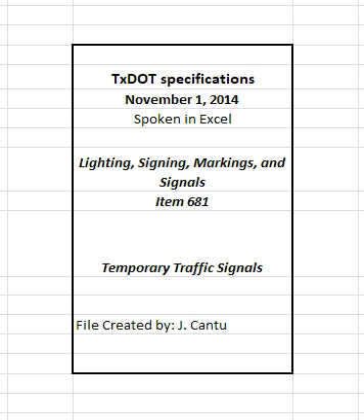Completely remove poles or other supports used for temporary traffic signals. When approved, concrete foundations may remain 2 feet or more below finished grade. Backfill the remaining hole with material equal in composition and density to the surrounding area. Replace any surfacing, such as asphalt pavement or concrete riprap, with like material to equivalent condition. Retain all removed temporary signal components, except for those furnished by the department, unless otherwise shown on the plans.